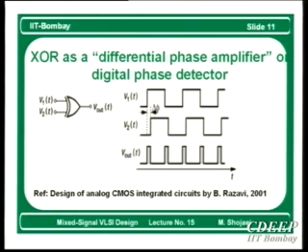You apply this signal to some oscillator which is controlled by this voltage. When a feedback loop is in a stable mode, you have an error, and that error is the signal divided by the loop gain. Now the loop gain is very high, so that error is very small. Therefore, if this delta phi is not very small, it won't remain stable. So this H should change, and to change this H means the frequency should change. What happens actually is that the frequency changes and then it comes back to this frequency.